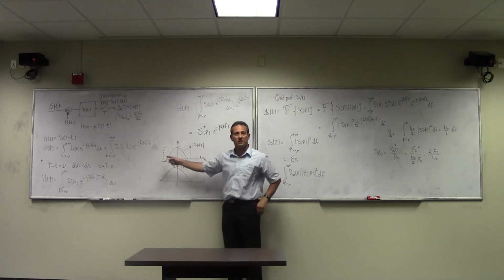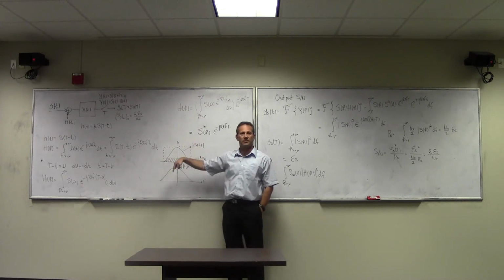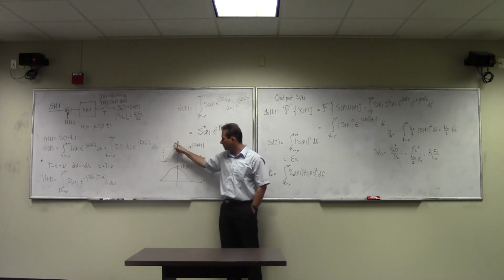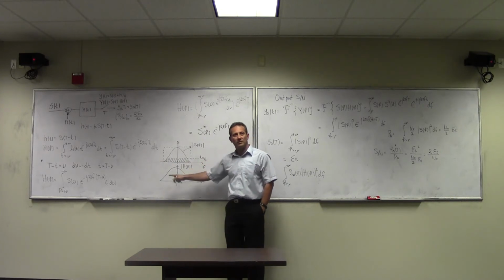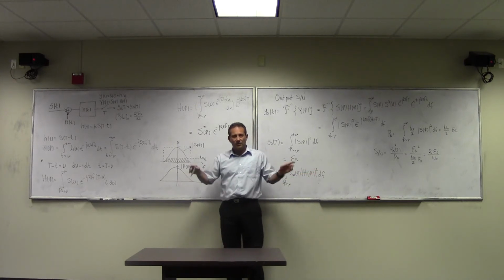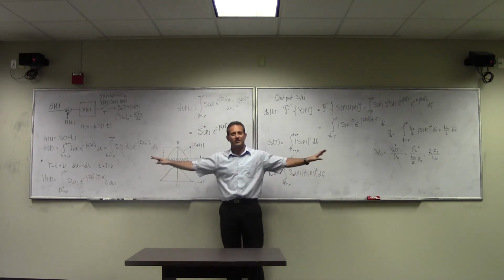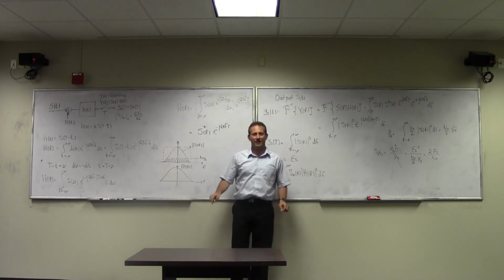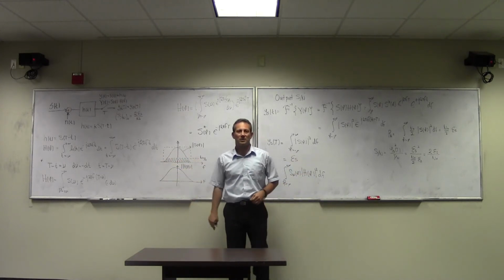If your signal is, let's say, square pulses in time domain, then guess what? Your matched filter is also going to be a square pulse. So in the frequency domain, you're going to have a sinc here, and your matched filter is also going to be a sinc filter. So it's going to make a door that will let the signal go through and all of its tentacles, right, all go through. And then the noise is going to be reduced as much as possible.